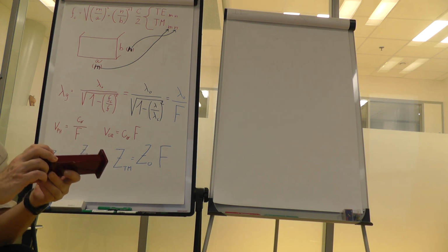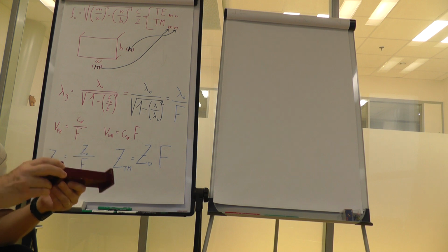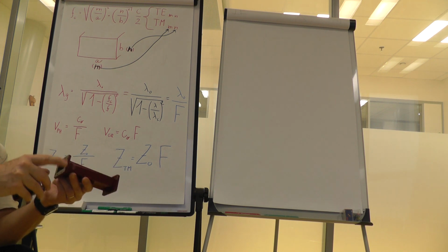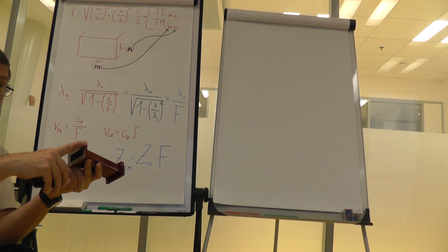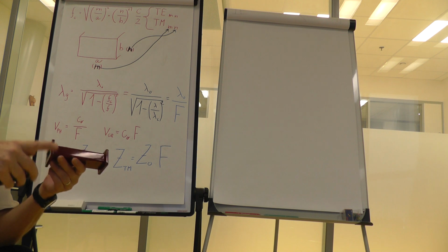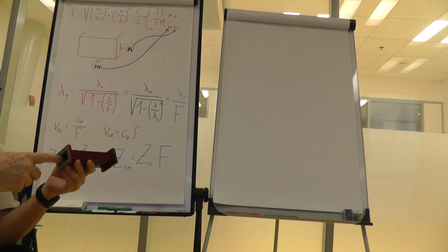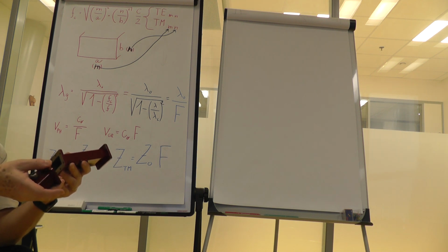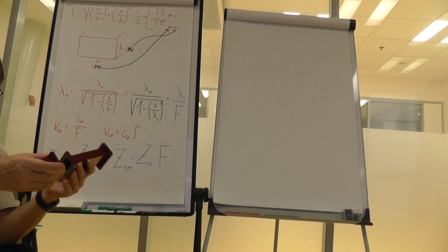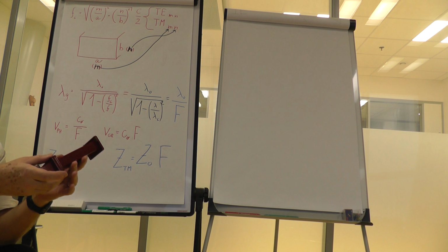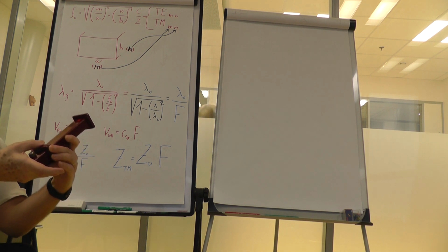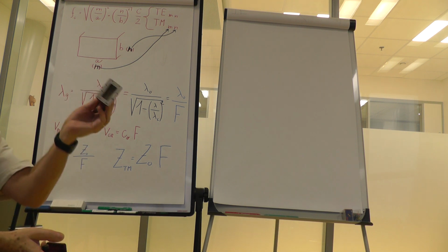And for even more precise waveguides, there is a special type of waveguide flange. It's a little bit larger plane, metallic plane, which has a disruption just a quarter wavelength from the waveguide, which in fact acts as a short, which I will describe to you only in the second part of this lecture using a Smith chart. So now this is a waveguide.